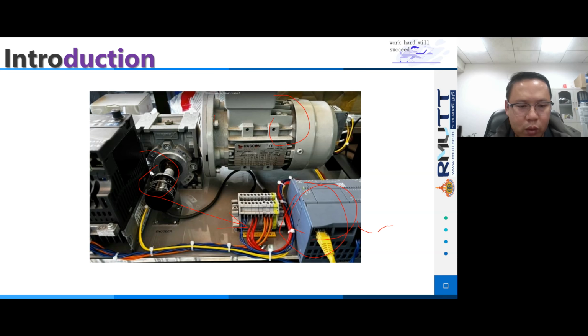along with voltage, and then the motor driver uses the control signal to drive the motor and adjust its position according to the new control signal. The feedback loop continuously updates the current position from the encoder. The PLC recalculates the error and adjusts the output until the motor's actual position matches the set point.